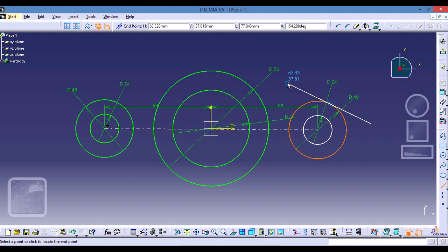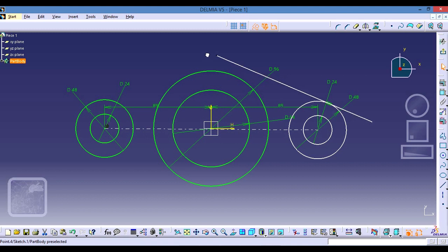The circle must be orange, so we can say that is touching the line, the circle, and we click again. And what we need to do is click on this part of the line to pull it like this, and then we need to stick this line to this another circle. Click on it, Control, keep it pressed please, and we're gonna click on the circle like this.